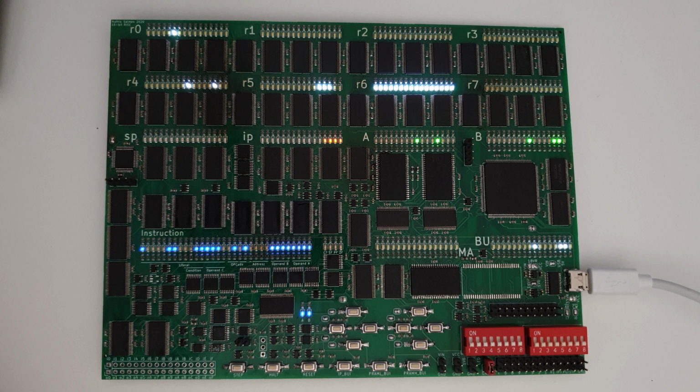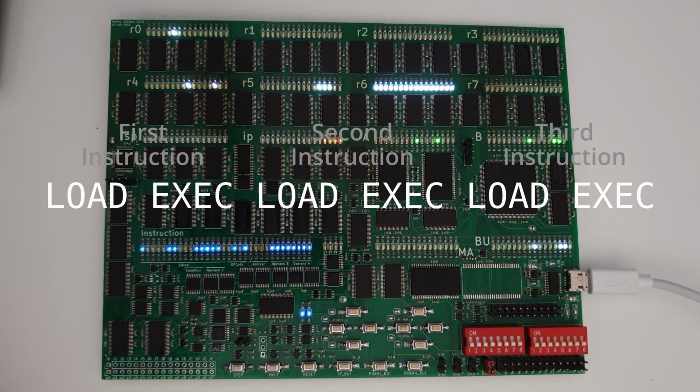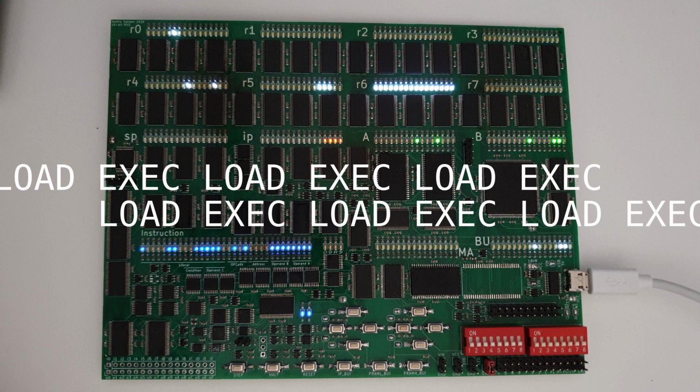Here we follow more of a RISC philosophy as compared to the last design, which was CISC. The last computer usually took around 5 cycles for a single instruction. Here a single instruction independently is finished in only 2 cycles. But it gets better. We do 2 of these load-execute cycles in parallel, meaning that one instruction is executed every cycle, while the next one is loaded simultaneously.